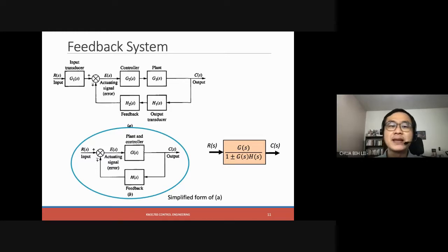We call it a feedback system format. This feedback system format is very common in control, because, as you know, at the beginning we said there is open loop and there is closed loop control system. If it is open loop, then you never check what is actual. You just turn on the current, or you turn on the fan and it will rotate. Whether it is rotating at the correct speed or not, we don't care. That is open loop.